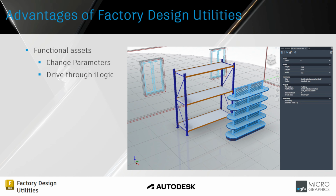Then the assets are also very functional. What I mean by that is, in normal Inventor design, when we want to change something, we go to our user parameters, create names for them so they're easily identifiable, and then either change the parameter individually by typing in a value, like for instance the height over here, 2,000, 1,500, 1,850, or we can make a multi-value user parameter, which allows us to set what we want the height to be. So I only want 3 heights: 1,800, 2,000, and 2,200.